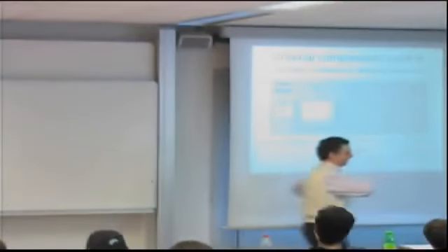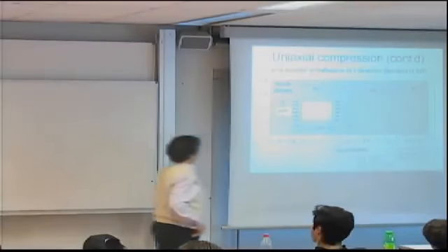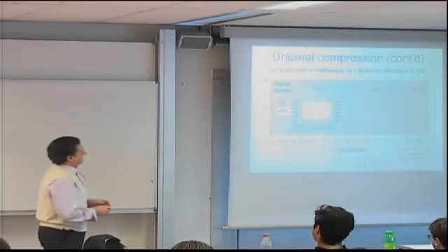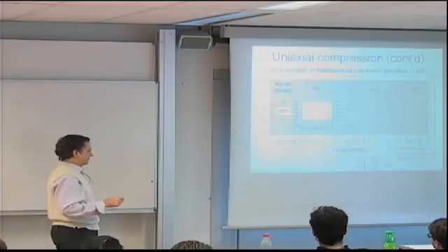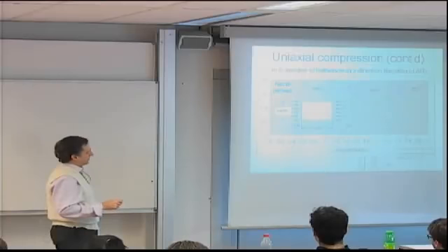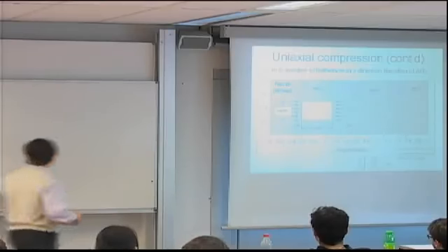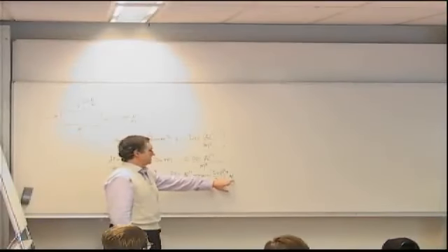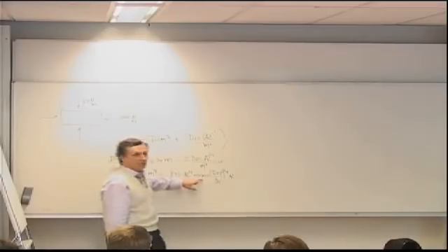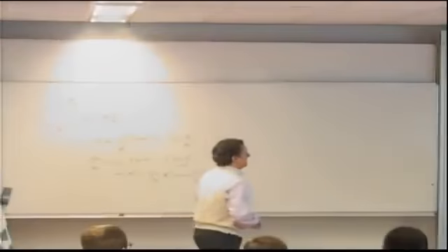Then we said, okay, if I plot, as a function of the aspect ratio, my buckling load for uniaxial compression, we find that depending on the number of half waves, or, excuse me, depending on the value of the aspect ratio, we can have different numbers of half waves that minimize this expression. Essentially, you can see it here. There's an aspect ratio here. As the aspect ratio is increasing, I would expect the M to also increase, and that's what this is saying. I'm increasing the aspect ratio, therefore the M that minimizes will also increase.